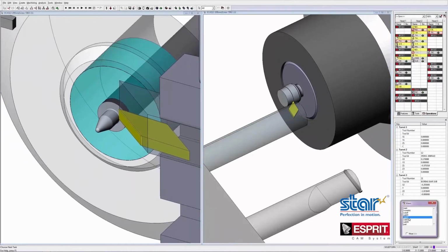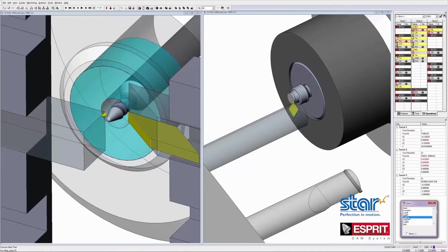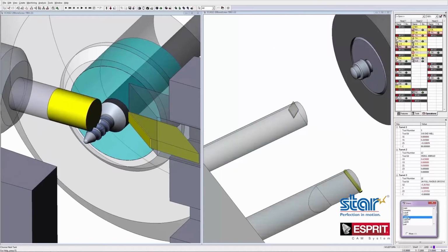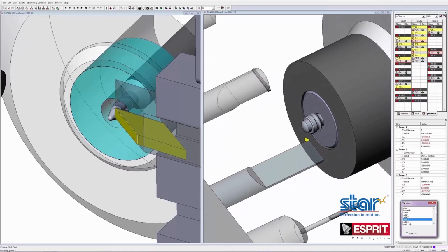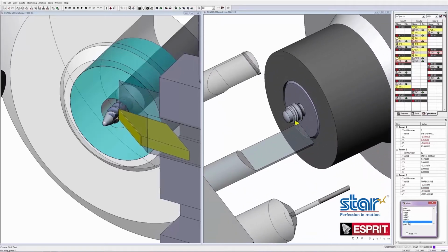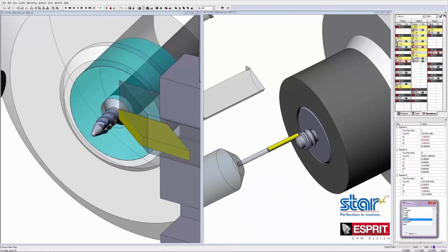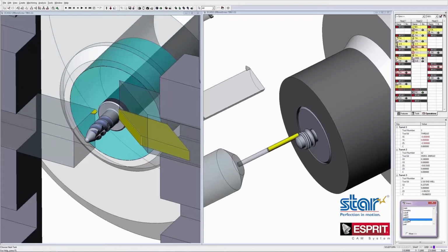If you have confidence that the machine is correct, if you have confidence that the code is correct, then you can set up the machine without much thought. You just need a roadmap showing you how the machine is set up. What tool goes where? Guide bushing or chucker mode? What size guide bushing? Ground stock or cold rolled? Proper documentation is next to godliness.